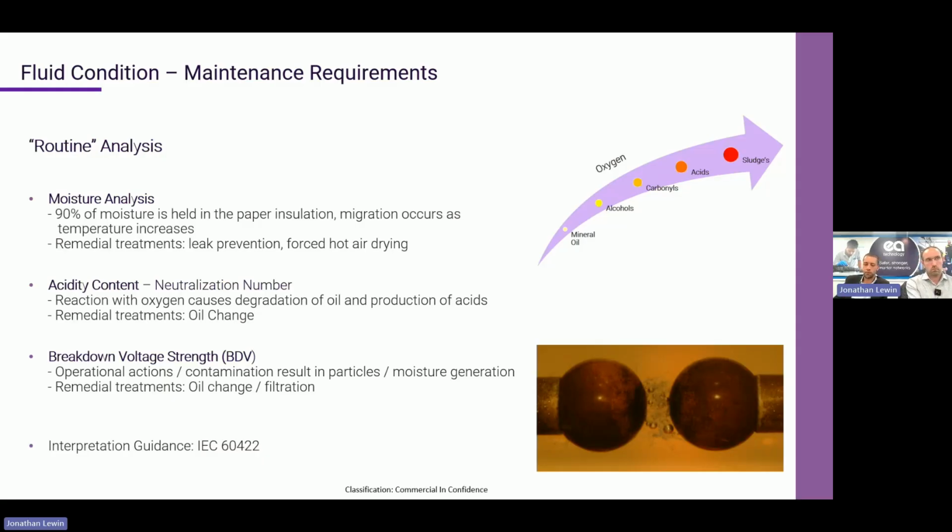That's important to determine whether you've got a high moisture due to internal degradation of the asset or whether you've got a moisture ingress issue in the asset, and the correct actions then will depend on the cause of that high moisture. Next up, we have acidity.